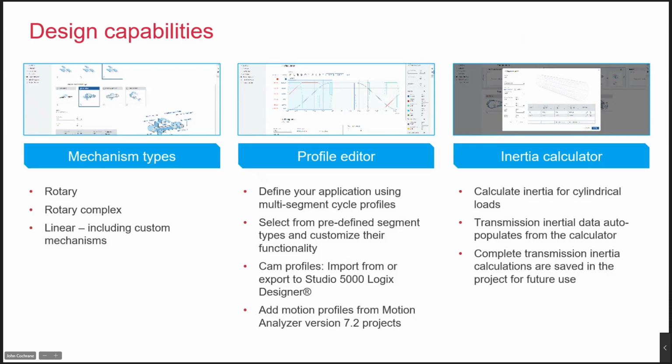You can also import cam profiles from Studio Logix 5000. So if you're using Studio 5000 Designer, you can create a cam profile there, import that in, and we can go ahead and size it based on the cam profile as well.